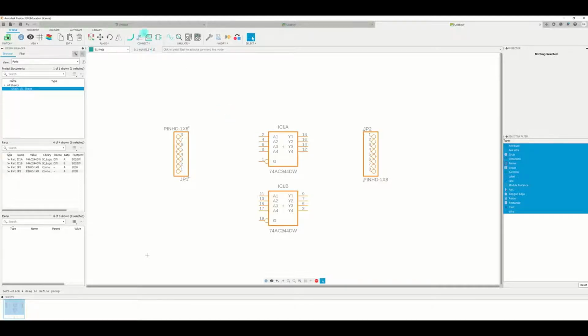So you have that. Okay, so let's try connecting these pins to the pins of the IC. To do that, you have to use the connect. In the connect you can make use of this net, not the line, but you have to use the net, so there'll be an actual connection. So click the net, and then you can select the type of net that you want. You can have straight, you can have bend, and so on. So let's try the straight one with a 90-degree bend.